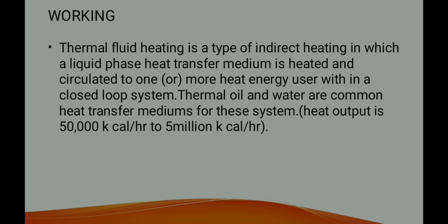The thermal oil or water are common heat exchanger mediums for this system. Basically, it uses oil or water as a medium. Actually, a thermal fluid heater has another name, heater oil, and the heat output will be 50,000 kilocalories to 5 million kilocalories per hour. This thermal fluid heater will act as a closed loop system.